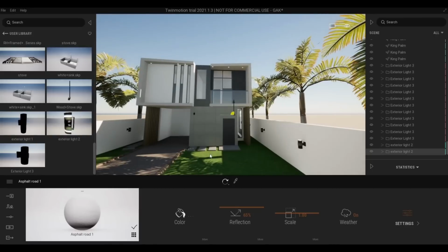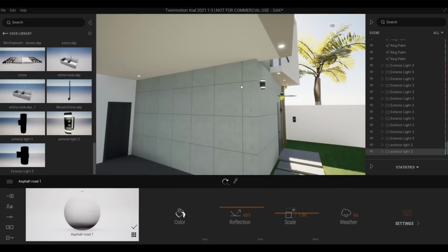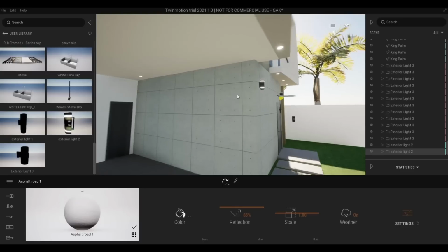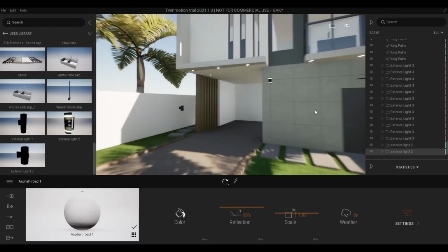But before I do that, that will be easy, by the way. You just need an extrusion, and then what you do is you just set the plane here, and then go to, I believe this is west or east from Revit, and then create an L shape or a 90 degree, something like this, and that will be good.